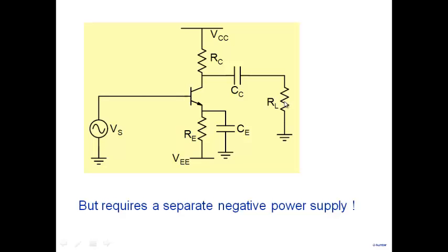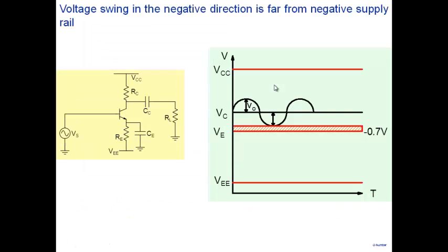I'm taking more power from the battery, delivering more power to the load. But how do you deliver more power to the load? Well, by building more swing, because note that power dissipated in RL is V0 square by 2RL. So you want to build more swing. So if you're increasing VCC and you're increasing the swing also, then maybe there's some justification. I'm taking more power from the power supply, also delivering more power to the load. But note here that when I added more power supply here, I'm not able to increase the swing of my amplifier.